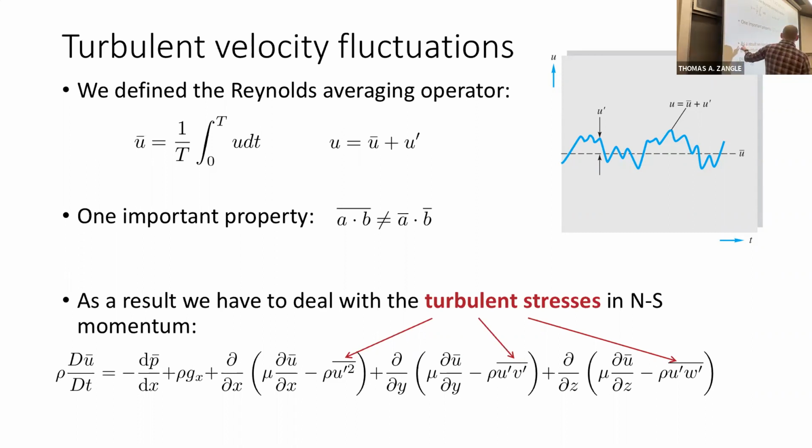And this is effectively the problem that we have to deal with when we're modeling turbulence: how do we handle the turbulent stresses? This is what turbulence modeling is all about, and it's what the problem of dealing with turbulence and simulating turbulence is all about in fluid mechanics.